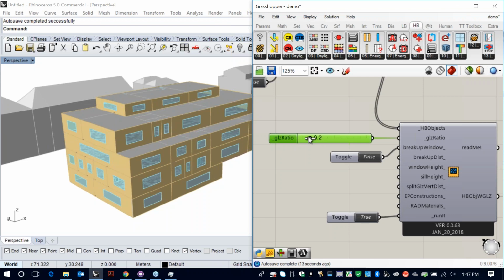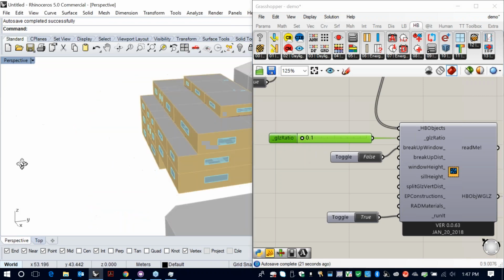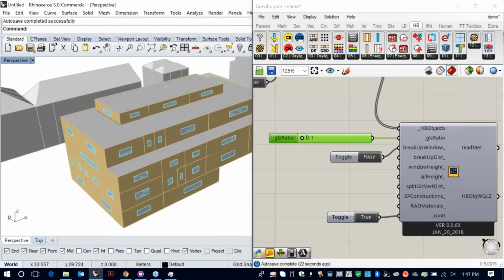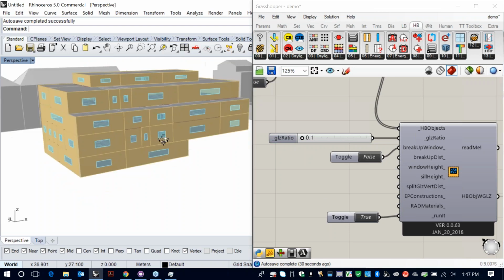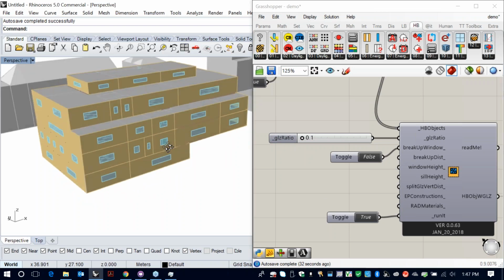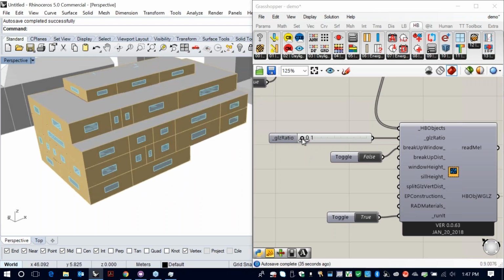And so this is meant to show you this type of workflow. As Michal said, this model originated in Revit, and changing the entire glazing ratio of a Revit model is something that's relatively difficult to automate. But because we've gone through this workflow, because Michal was able to create a clean gbXML using Spider, and because we were able to import it, we can now actually set up an entire simulatable model like this with a parametric glazing ratio pretty easily.